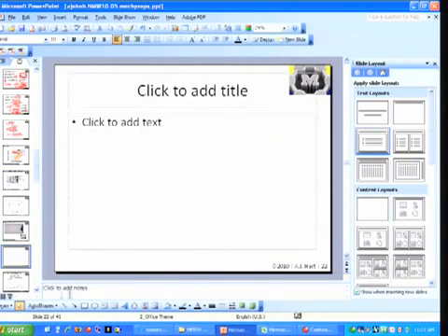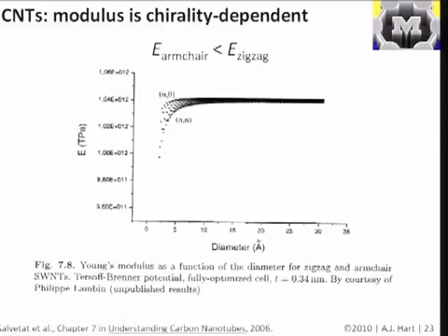So I've sort of built us up to think that we can consider a nanotube or a nanowire as a beam, just like a macroscopic cantilever, the same kind of picture that comes from basic mechanics class. And it turns out that that's totally true unless you get down to really, really small structures, or unless you deform the nanostructure in ways that go beyond the conventional elastic limits. But just to say a couple important things about this picture, we do have to consider what the effective properties of the nanotube are.